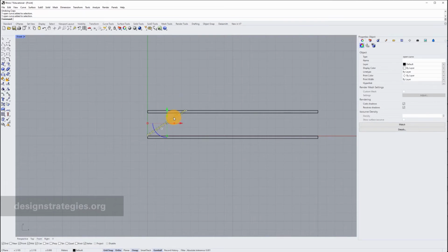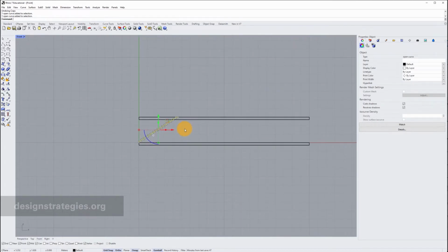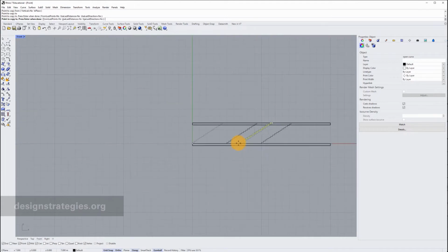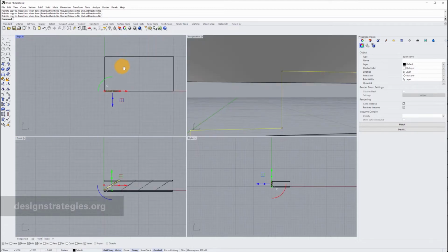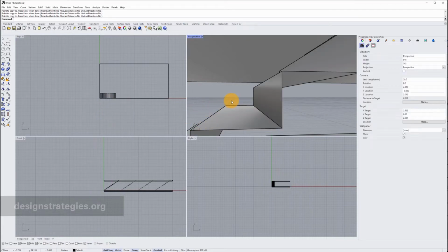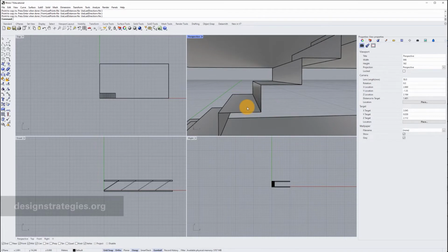There are several ways of how to draw a staircase, and I copy this one from here, and I copy some of them to have several options to try. And the first one we would like to look at in our floor plan. I want to extrude this to 1.5 meters. I have to do it in minus 1.5 because it points in the minus direction. And now I extruded this to 1.5.